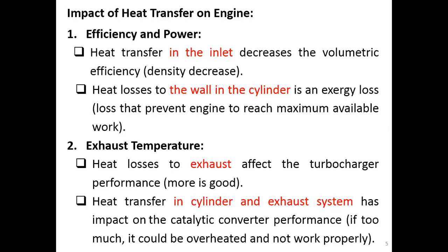If you have more heat transfer in the cylinders and also in the exhaust system, more heat inside the cylinder then goes to the exhaust system. This amount of heat transfer will have an impact on the catalytic converter performance.